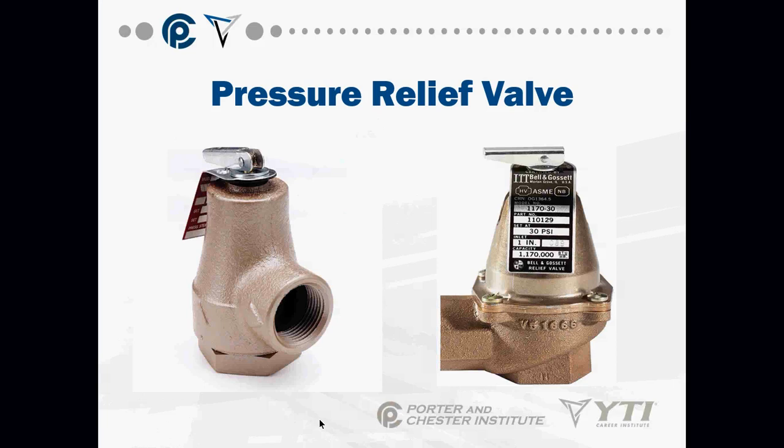You said that the previous one, the pressure reducing valve, is usually not in a residential, but we're talking about pretty low pressures on these things with the pressure relief valve, and most houses with city water is 55 to 60 psi, and wells are even 50, 55. So why wouldn't they all have a pressure reducing valve? Because you are using the water feed valve as a pressure reducing valve in a residential setting.